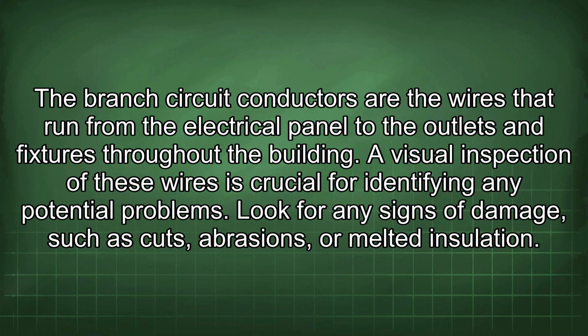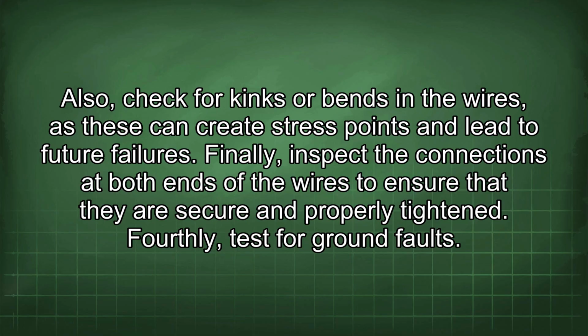Look for any signs of damage, such as cuts, abrasions, or melted insulation. Also, check for kinks or bends in the wires, as these can create stress points and lead to future failures. Finally, inspect the connections at both ends of the wires to ensure that they are secure and properly tightened.